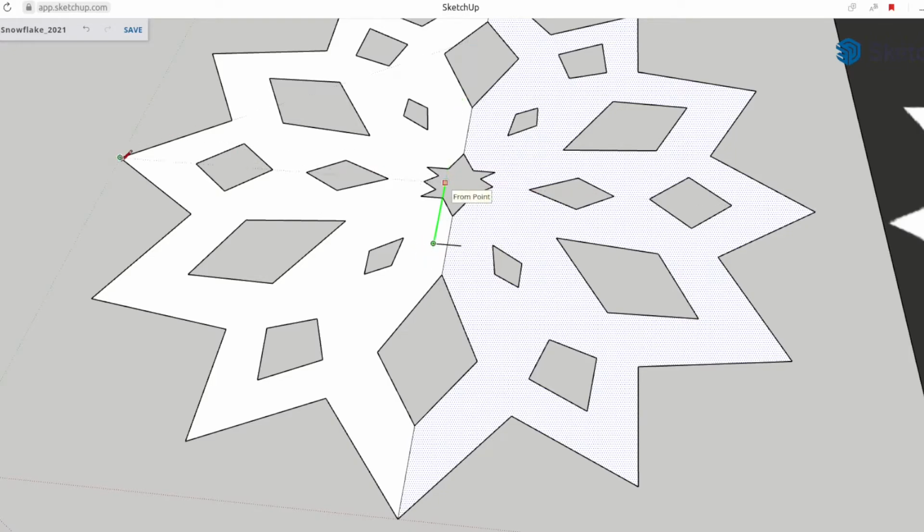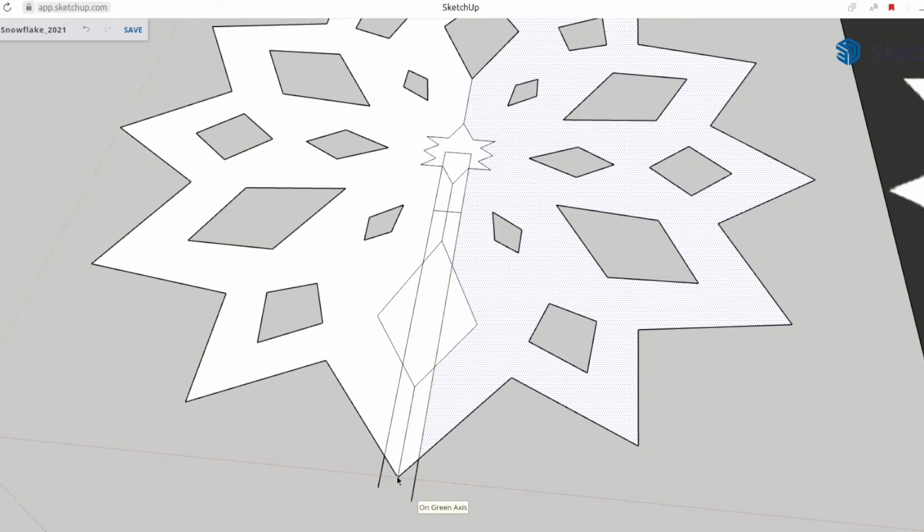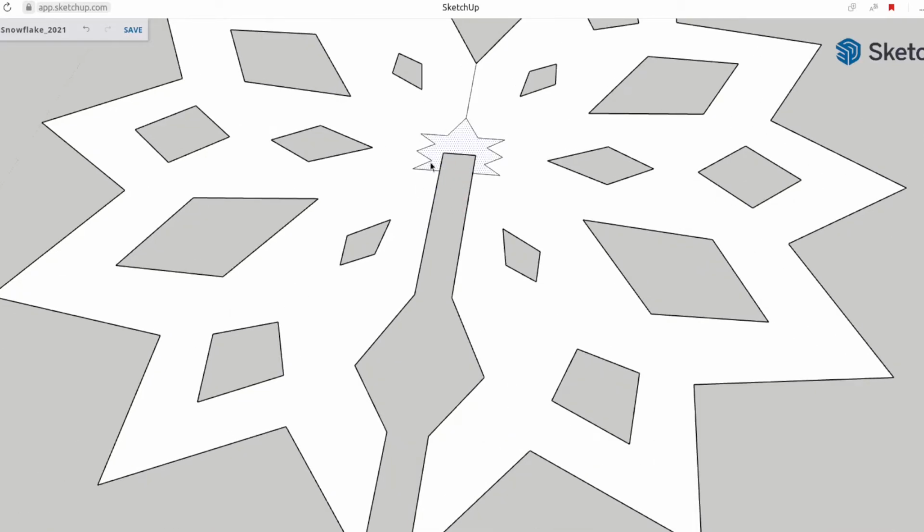So get this to the middle, and then get this all the way out. And then this has to go over. You use the snapping feature in SketchUp to do all of this. And you just purge all of this in here. Purge all of this with your erase tool. That line, all of these lines, that line, and that line. And actually, you get rid of all of that.